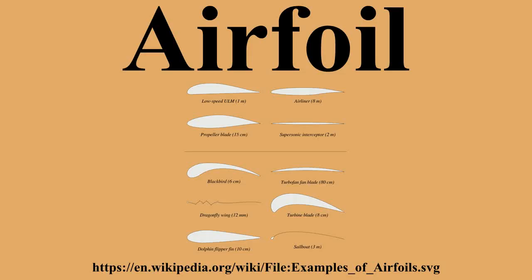Modern aircraft wings may have different airfoil sections along the wingspan, each one optimized for the conditions in each section of the wing. Movable high lift devices, flaps and sometimes slats, are fitted to airfoils on almost every aircraft. A trailing edge flap acts similarly to an aileron, however it, as opposed to an aileron, can be retracted partially into the wing if not used.